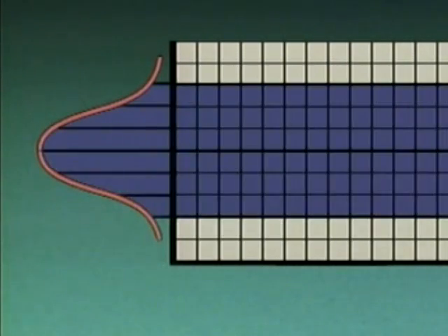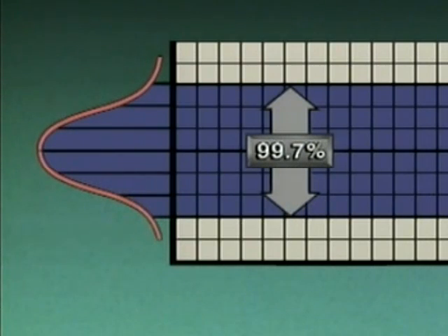The area between the upper and lower control limits, or the lines for 3 standard deviations, represents about 99.7% of all random occurrences. Now, there's a remote chance that a point could fall outside of the upper or lower limit when only normal variation is present in the process. But keep in mind that the chance of that occurring is very slim. So, for all intents and purposes, whenever a process is occurring with normal variation alone, basically every point that's plotted on the control chart should fall between the upper and lower control limits.